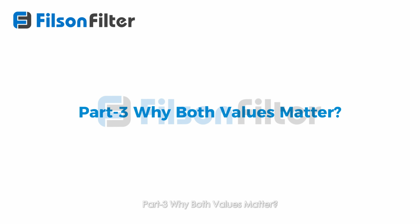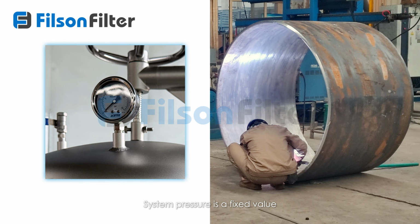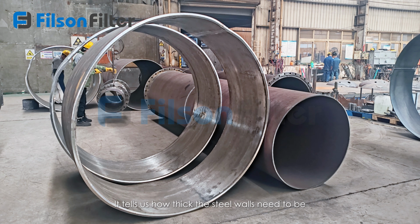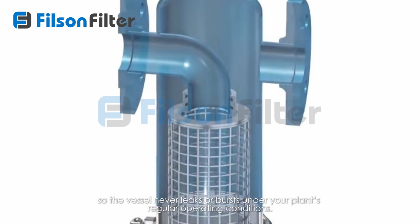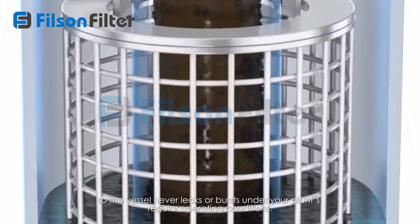Part 3. Why both values matter? They are related, but they are not the same. System pressure is a fixed value and mainly affects the strength requirements of your filter housing. It tells us how thick the steel walls need to be and what ASME flanges to use so the vessel never leaks or bursts under your plant's regular operating conditions.